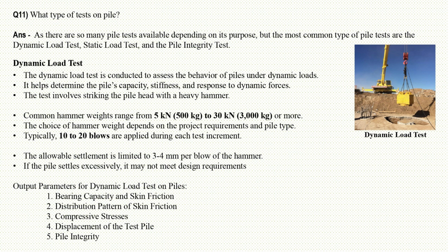Output parameters for dynamic load test on piles. 1. Bearing capacity and skin friction. 2. Distribution pattern of skin friction. 3. Compressive stresses. 4. Displacement of the test pile. 5. Pile integrity.